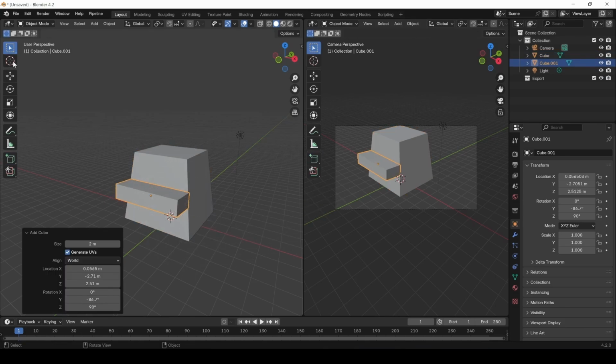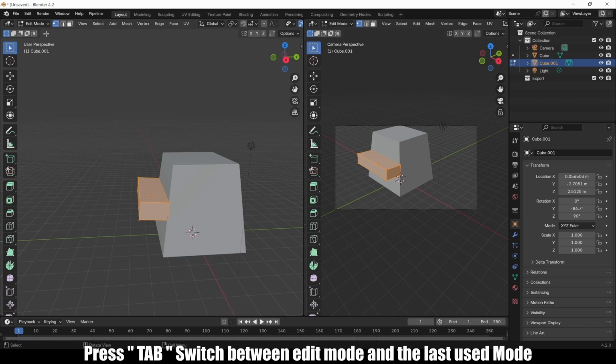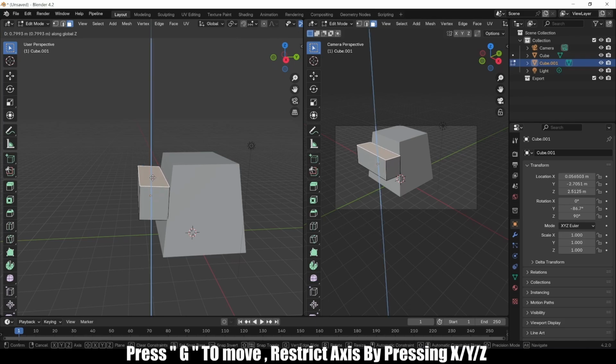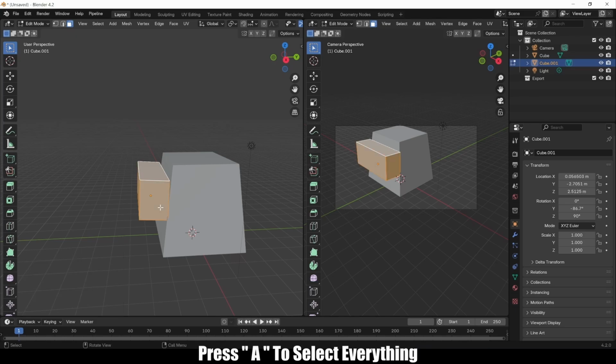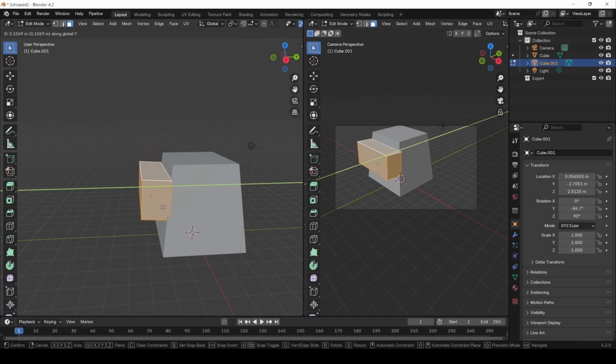Okay, go to selection again, select this object that you just created, enter edit mode by pressing tab, then if you are on vertices mode, press 3 to go to face mode and just select the face, J and Z to move it up to here, then press A to select everything, then J and Y to move it on Y to make it a little bit inside.